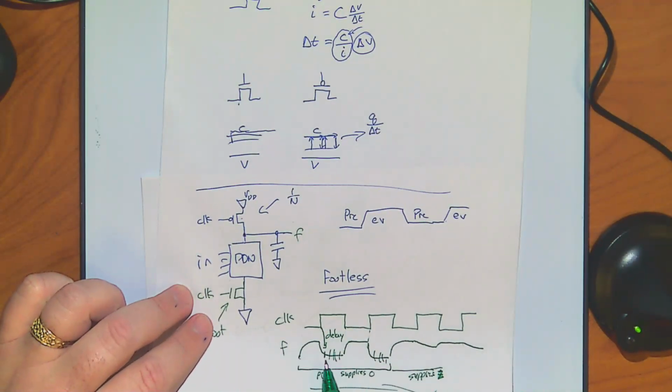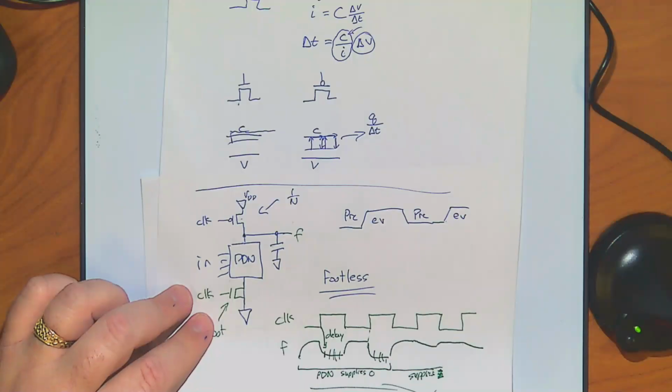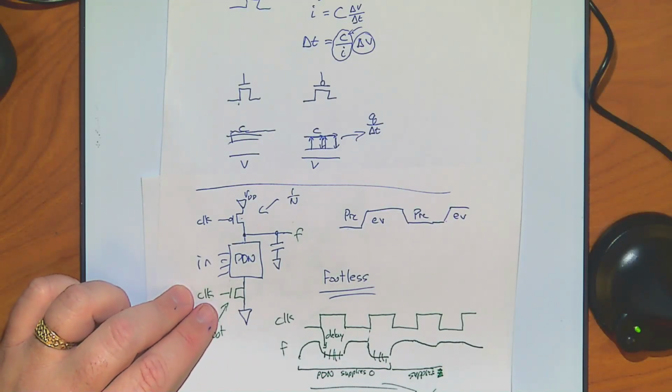We can put a delay in so that it doesn't see that discharge, so you can avoid some of the problems. The other thing that I could do besides the delay is what domino logic does. They just put an inverter, a static inverter on it. A static inverter is really small and it's really fast. It now creates a buffer between the two, and it basically makes it clean so this doesn't have a problem, which means you're always initially supplying that 0 and you've got a delay that takes care of it, right? So you can cascade dominoes, which is just everything we've done here, just put an inverter between it.